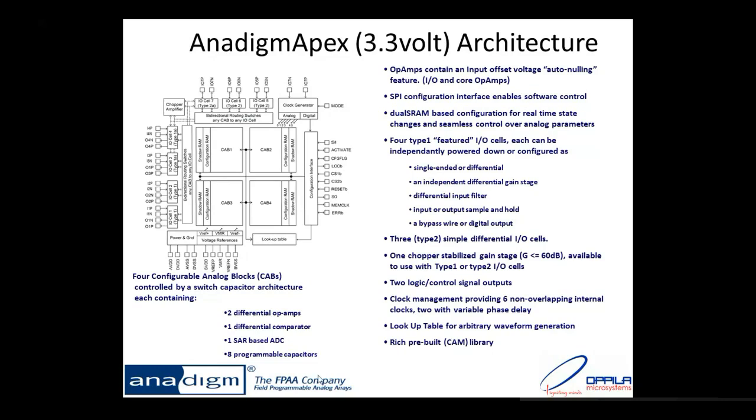Once these resources are exhausted, you can't design any more or use any more. You have to go for the next, adjacent FPAA. You can cascade those two FPAAs, so the output of FPAA1 can be given as an input to FPAA2. So you can cascade adjacent FPAAs and design much more complex circuits if your application demands.